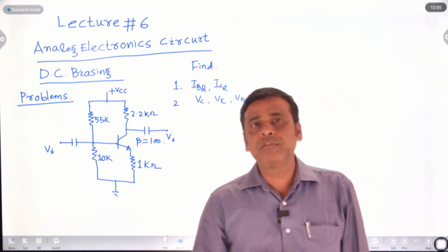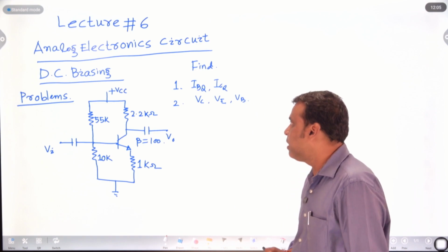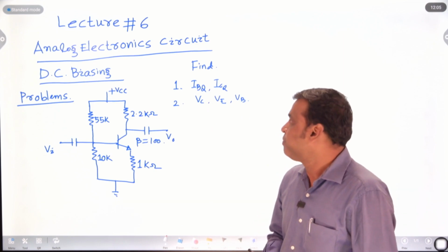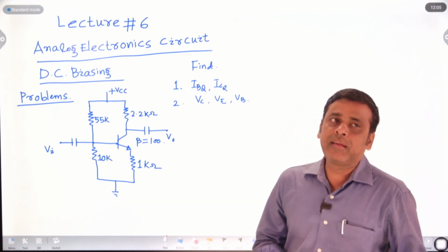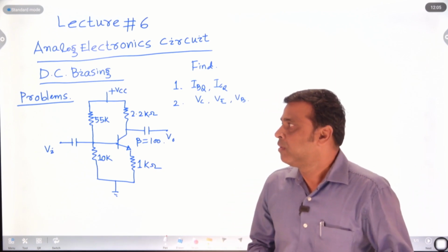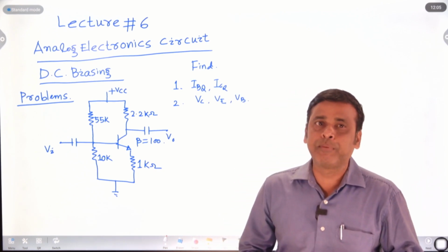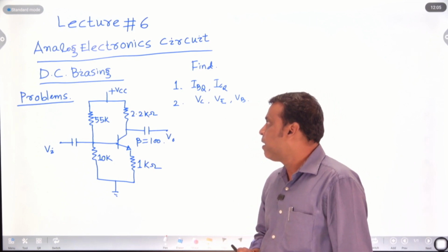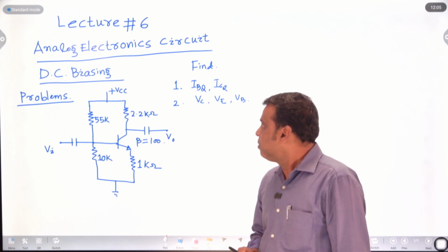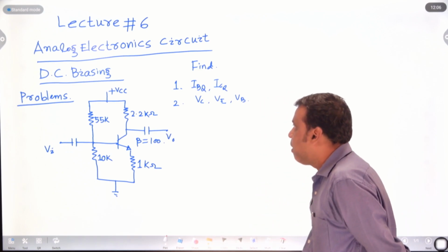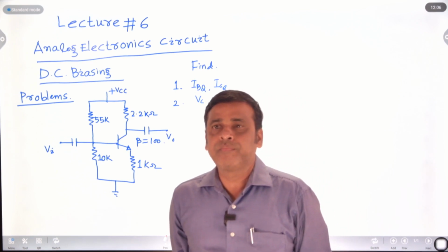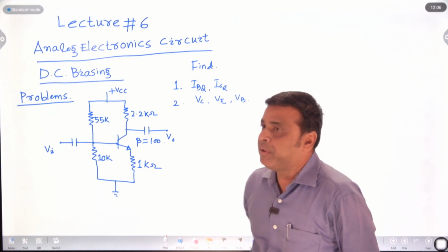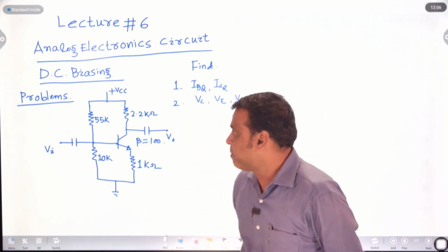Transistor as an amplifier means what? Amplifier means raising the strength of a weak signal. Once we get the amplified output, without disturbance, exactly the same as the input, without change in shape, we are just magnifying its amplitude level. We can say the input is amplified by the amplification factor. In voltage divider biasing, the operating point or Q point, which is the zero signal values of IC and VC, is more stable compared to fixed bias and collector to base bias or feedback bias.